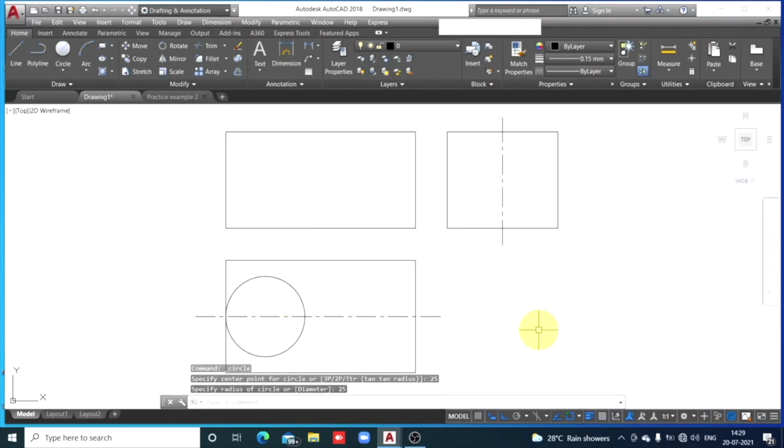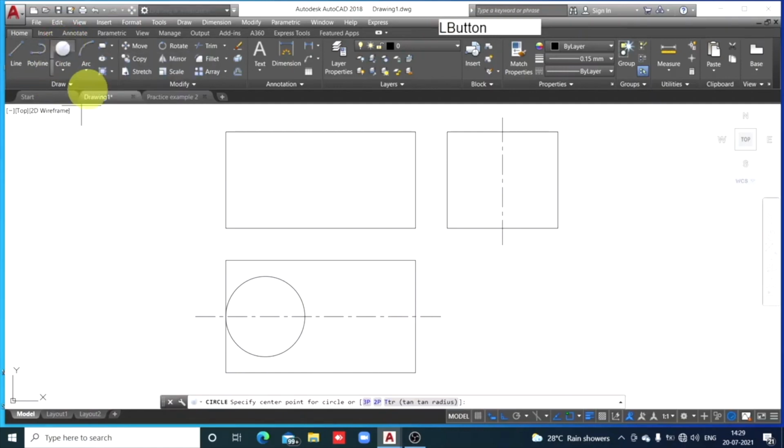Now on the right side, its curved edge of radius 35. So I have selected that command circle. From the midpoint of right edge, move cursor on the left side, that is you have now tracking line there. Check that green triangle. So you have selected that green triangle, that is the midpoint of the right edge. That midpoint of the right edge is on the axis of symmetry.